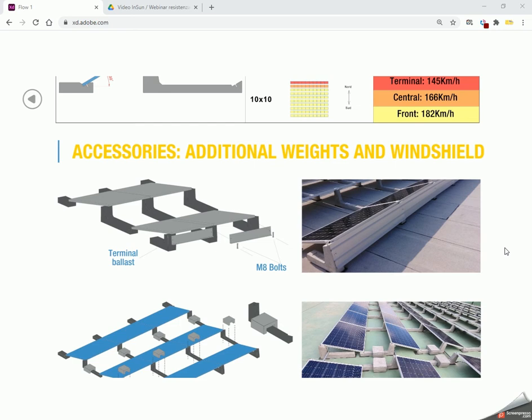The first attachment, as you can see, is a sheet metal windbreak cover that is put on the back of the ballast in order to close the rear end. By using this attachment, also proven by the fluid dynamic test, we notice a reduction of the wind coefficients. So, it becomes a very important attachment when you have a peculiar windy situation.